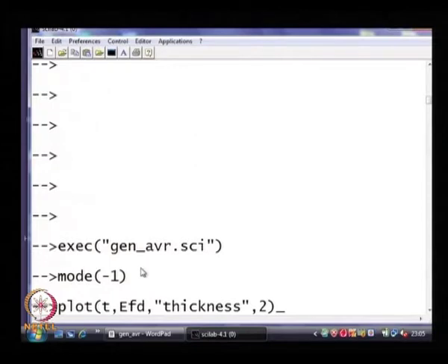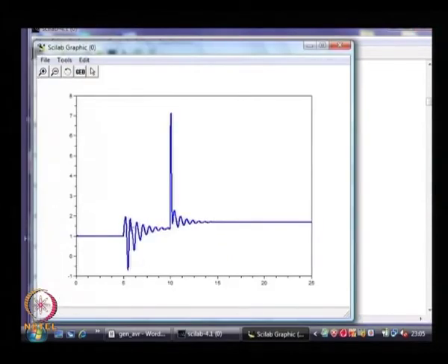Now, let us plot how EFD looks. Okay. Now, remember, at 5 seconds I have increased the torque, and at 15 seconds I have increased the reference value of the AVR, Vref. In both situations, you will notice that whenever there is a change in the loading of the machine at 5 seconds, the EFD changes from 1, which is the value under no load conditions, automatically to around 1.5. Okay. And if I change the Vref, that is the reference voltage of the synchronous machine, again EFD changes.